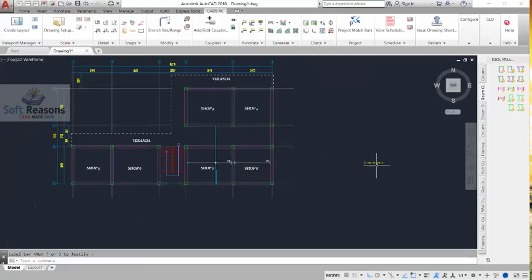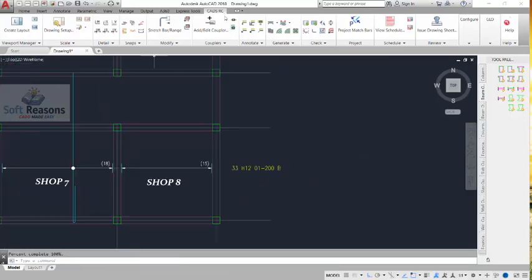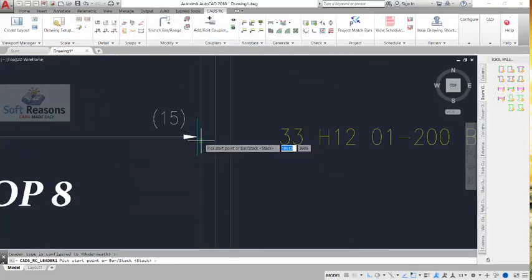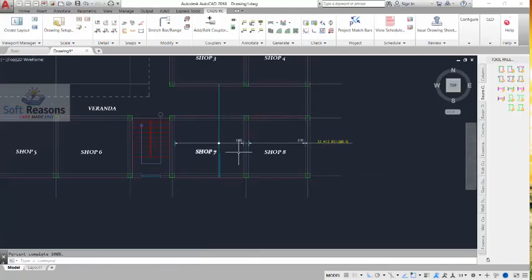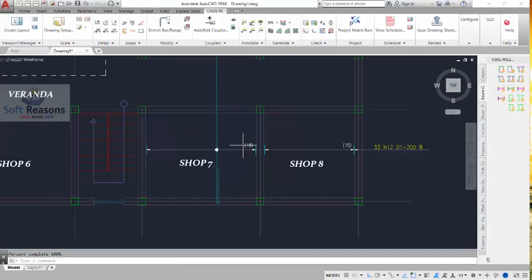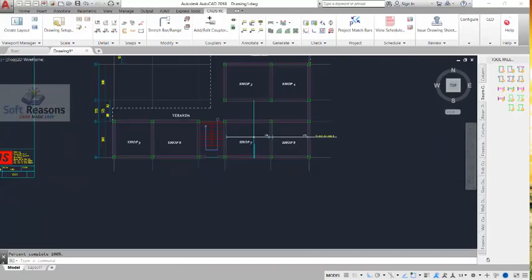All right, so click here to have the bar. So you have to now move this close just like this, and then you use these options where you have a leader option. One, click right there, pick this first point of the arrow and take it all the way to this point and click, escape that, move this on top of the line, the leader line successfully. So we have gotten our bottom reinforcement, okay, running from this panel successfully.